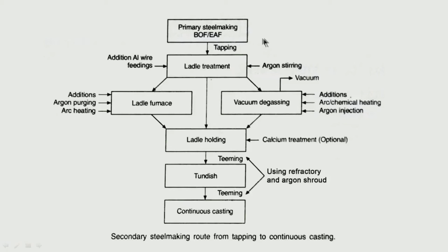Some of the refining processes are affected here. Dephosphorization is not very good if the liquid steel temperature is high. The erosion of refractory is also high, so the steel becomes more dirty. So, the temperature at the end of BOF should not be very high. It is very easy to control temperature here, because more oxygen is put in, and oxygen combining with silicon, carbon and so on makes the temperature go up, because of the autogenous reaction; a lot of heat is generated. But unnecessarily we should not go to very high temperature.